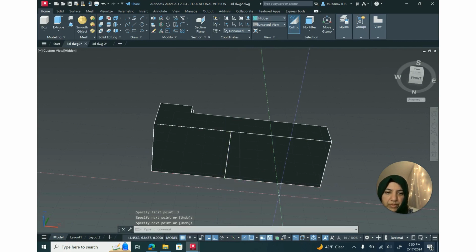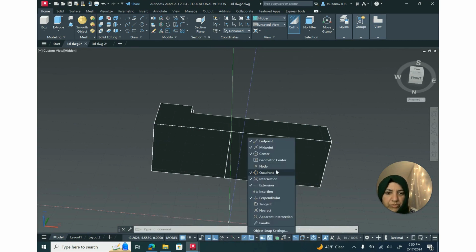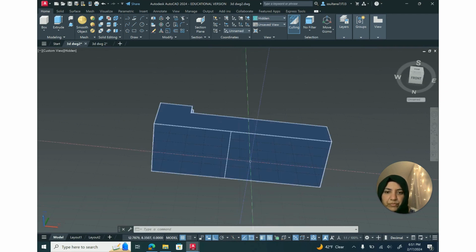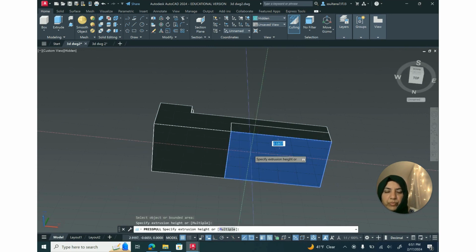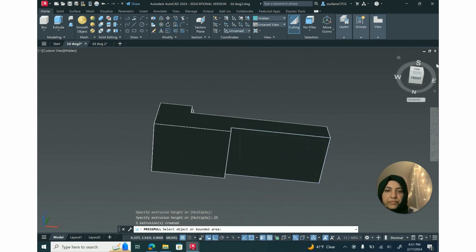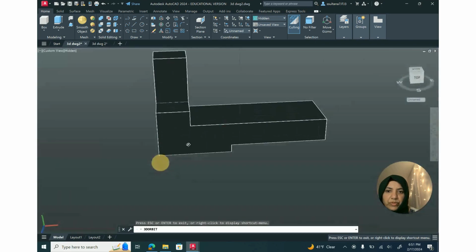snap. So for that, in your object snap settings, you need to have perpendicular checked and midpoint checked as well. These are the settings that you need to have. Now using the Presspull command, you can hover in the center somewhere in between the rectangle, and when it's highlighted, then you're going to press by 0.25.